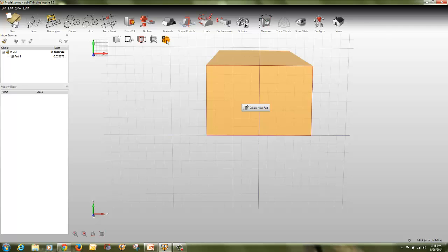As you sketch, Inspire automatically applies many sketch constraints for you. This behavior can be disabled using the preference window, which can also be used to modify the default angle measures for certain constraints. When you are finished sketching, right click to exit the active sketch tool. At that point you will still be in sketch mode and may either select another sketch tool, click on a sketch curve to edit it, or right click a second time to exit sketch mode entirely. When you exit sketch mode, the push pull tool is automatically activated so that you can immediately push or pull your sketch into a solid.